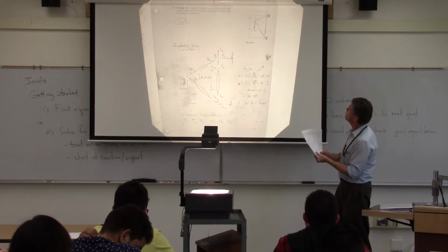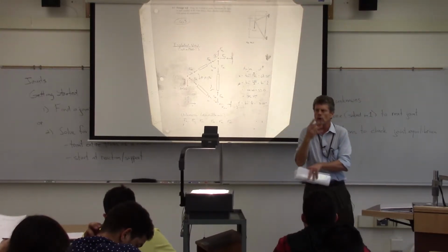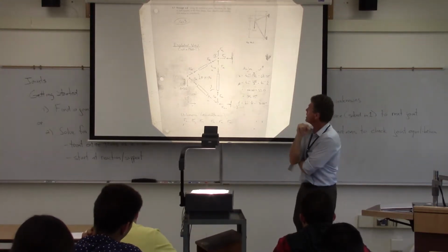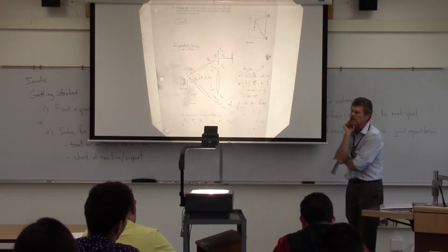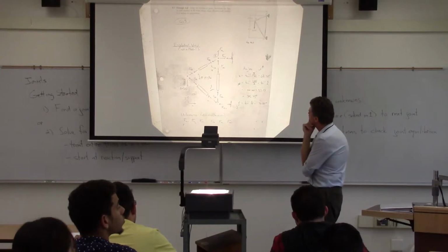Okay, so what we're doing is solving for this truss. We're basically solving for the forces in those members. And again, as a designer, you probably use the method of statics to come up with sizing those members before you actually design them and throw them into a finite element program.